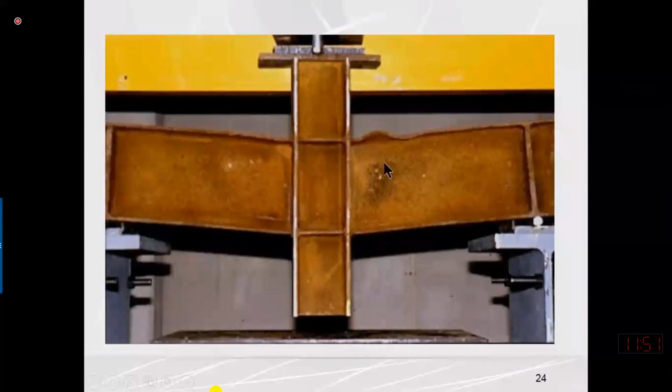So this is referred to as local buckling because the flange bent only at a small portion. Why did it bend? Because the b over t ratio of this flange, or bf over 2tf value, might be larger. If we want to avoid this, we need to reduce the b over t ratio, either using a thicker flange or reducing the flange width.